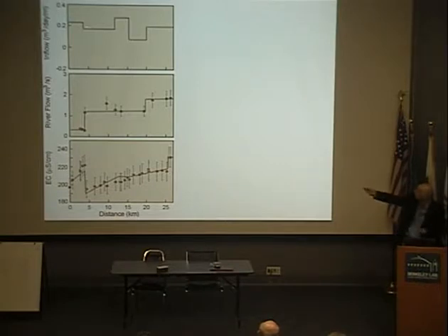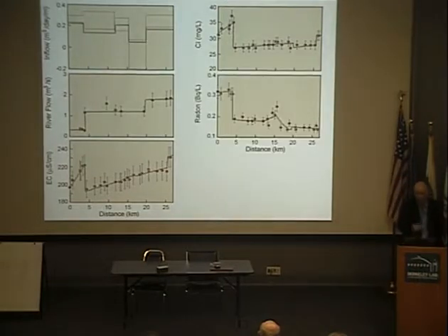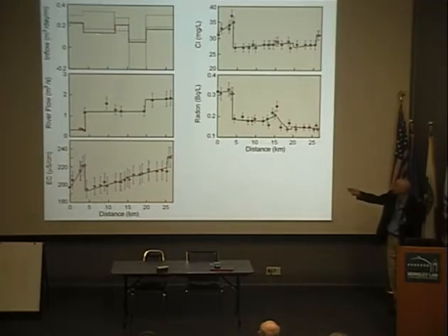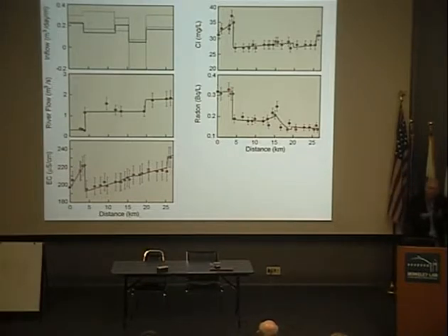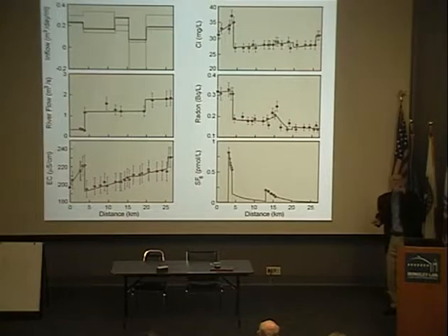It's all inflow, around about 0.2 cubic metres per day per metre. We add chloride and fit the model again, and you see the inflow rate changes. We can add radon, refit all of the data, and we get a slightly different picture. The black one in each case is the most recent estimate. And you can see, if we add more data, we get a slightly different picture. If we also do our injected tracer, we again get a slightly different picture.